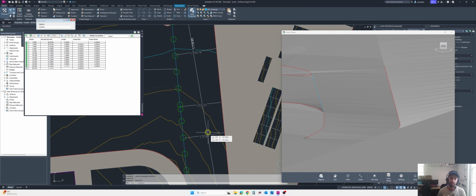We design the horizontal alignment, vertical alignment, and assemblies. Then we can have 2.5% properly. This is for the earthwork analysis and for the proper grades, to see where the site is sitting at the moment, if we don't have too much cut or too much filling area.